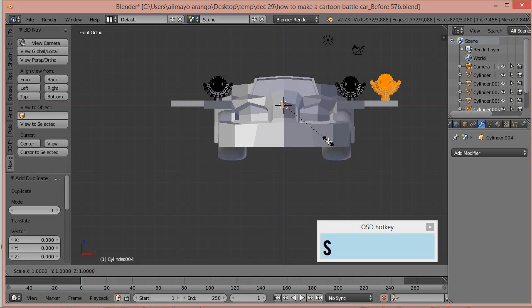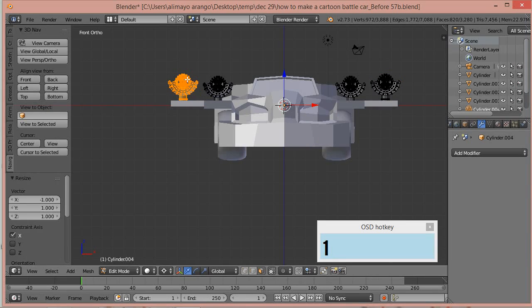Now we're going to press S to scale on the x-axis -1. Left click to lock in. Most likely the faces, the normals, aren't right, and if we look at it, it'll look strange. So we're going to press Control N now, and you can even kind of see there that looks like it dealt with the situation of the normals not facing the right direction. Normals, by the way, are just the direction that polygons face. Sometimes they can get mixed up where they're facing in instead of out. So that's what normals are.